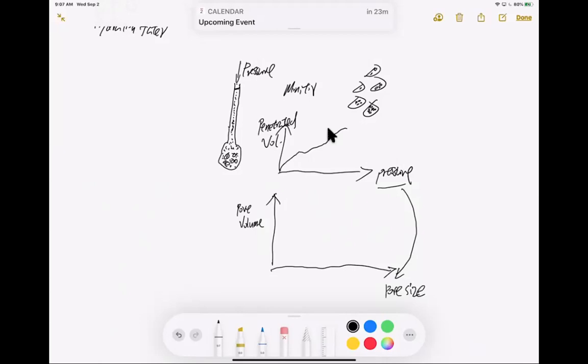Okay, so based on an equation called the Washburn equation, so you don't need to remember the name, we have a correlation between the pressure and the size of the pores. So basically, the smaller the pore size, we need higher pressure to push mercury into the pores. Okay, so from this curve, we can have another curve, which is pore size versus pore volume. Okay, and from there, we can know what is the porosity, how much volume of the pores in our sample, as well as for certain pore size, what are the pore volume. We also call that pore size distribution.